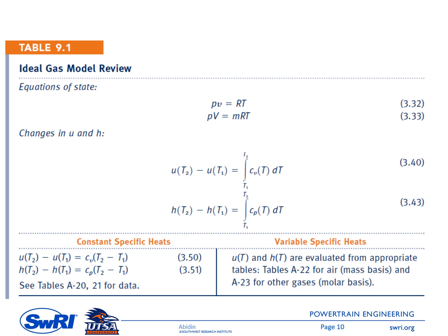So it means it is R0 over the molecular weight of air. R0 is the universal gas constant, 8.314 kilojoule per kilomole Kelvin, and the air molecular weight is 28.97 kilogram per kilomole.